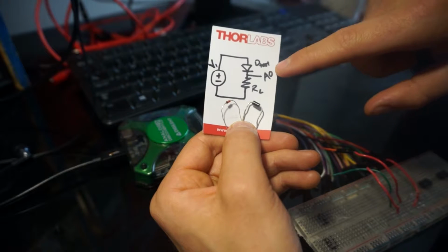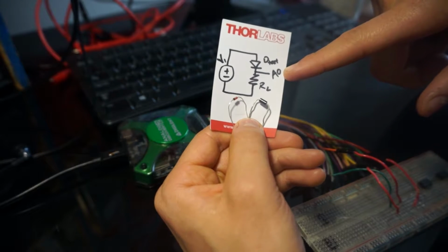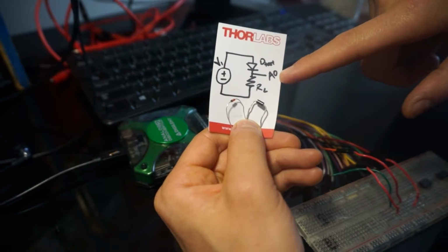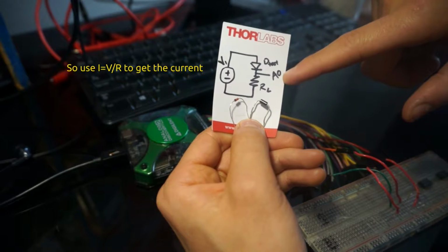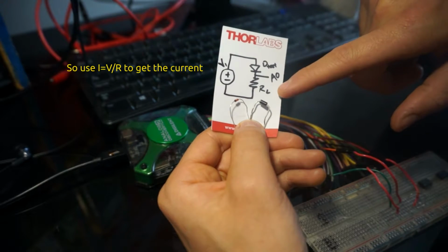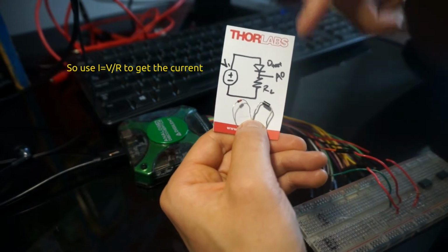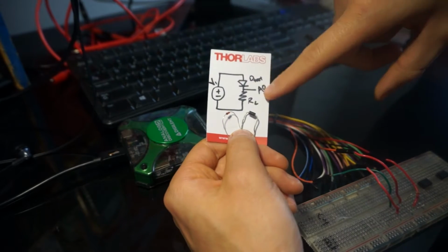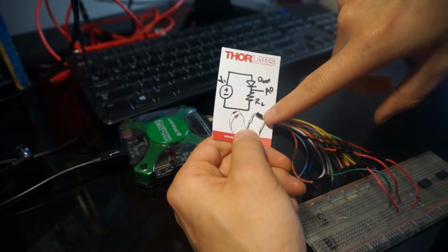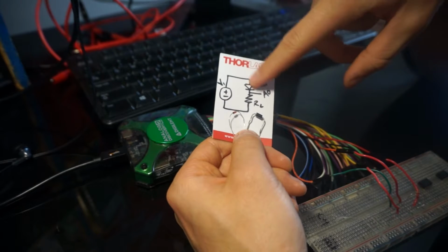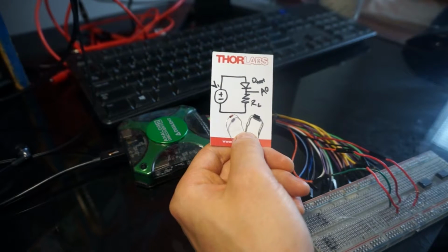And then to get the current, we'll take the voltage across the resistor, which is also at that measurement point, and of course the other side's the ground. So we have the voltage across it, and we know the resistance value because we can just measure that. So yeah, and then all we're going to do is switch out a couple different diodes, these two different guys right here, and look at their curves.